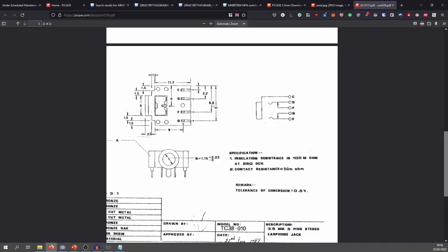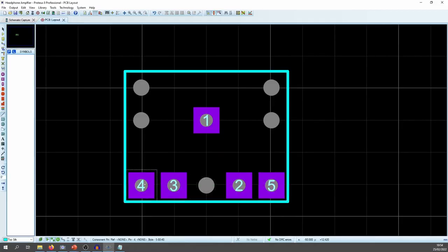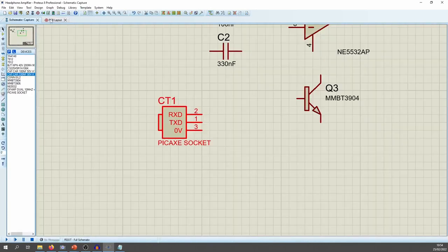And that says 7.7, so very, very close. And the last one is 10 millimeters pin to pin, and that's 10.16. So it's very, very close. Usually you would make a footprint that's bang on that part, but because I'm using a default library footprint, again, I'm pretty sure it's going to work in this case.